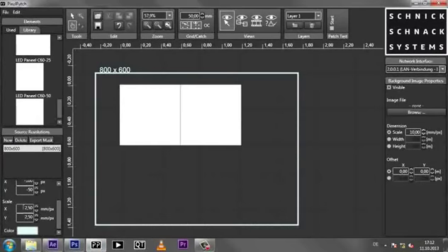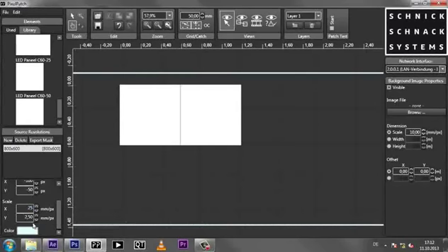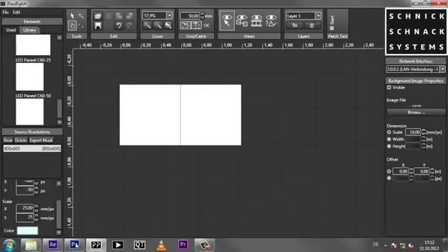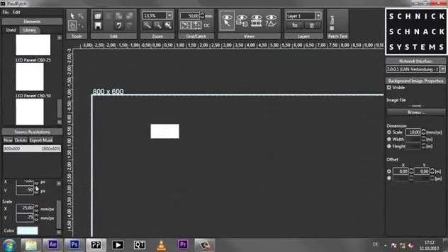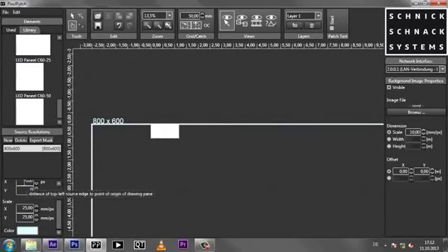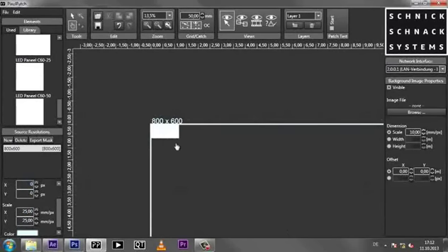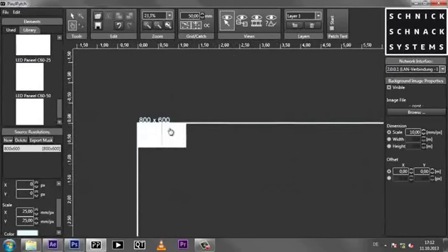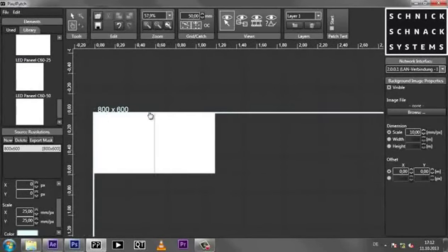So what I do now is I change back to the default value here, 25 millimeters per pixel. Well, looks big. And then I put my offset on 0. So as a result, it starts here in the upper left corner, and every pixel has its equivalent in a real LED because it's got this 25 millimeters, which is the physical distance between two real LEDs on my panel.